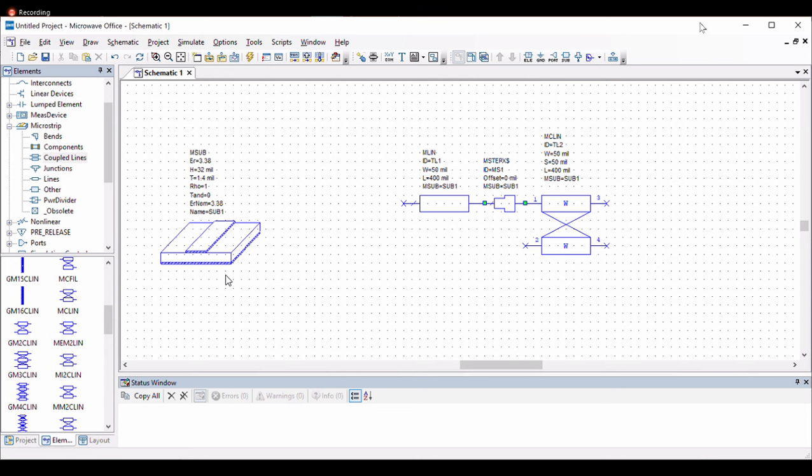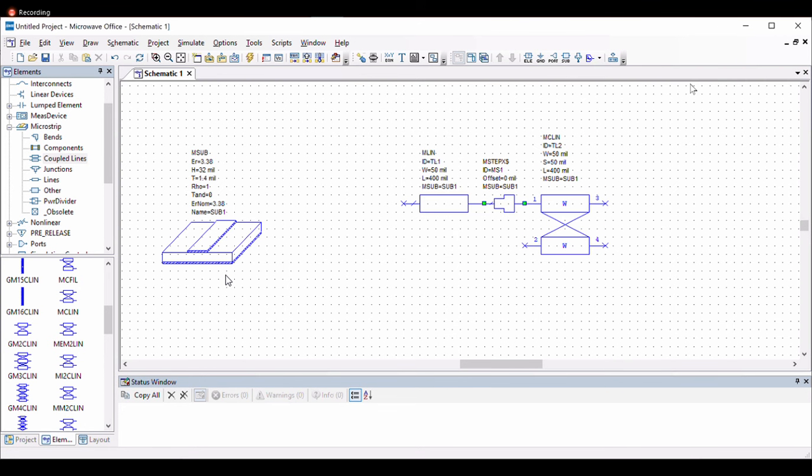So one more thing. Yeah, go ahead. When it comes to the coupling of the transmission lines, is the desired spacing a function of the wavelength or the frequency you're working with? The spacing is how much coupling you want. Right, but let's say you wanted a certain coupling factor. Would you have to change the spacing if you were working with a higher or lower frequency? No, you change the length more.